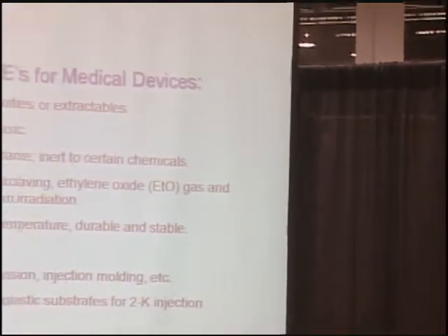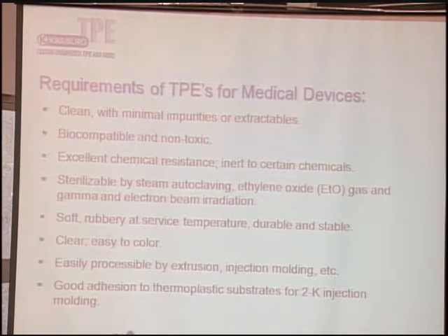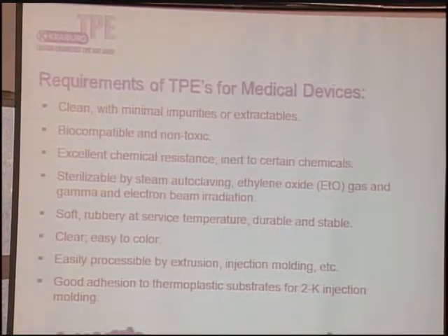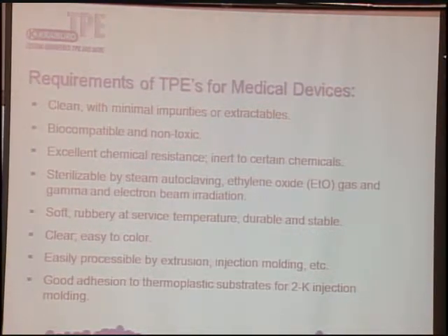And the requirements for TPE for medical devices, they have to be clean with minimum impurities and extractables. That's a very straightforward requirement. They have to be biocompatible because those materials are usually getting direct contact with skin or with the body parts. They have to be non-toxic. And in many cases, they also have to have excellent chemical resistance.